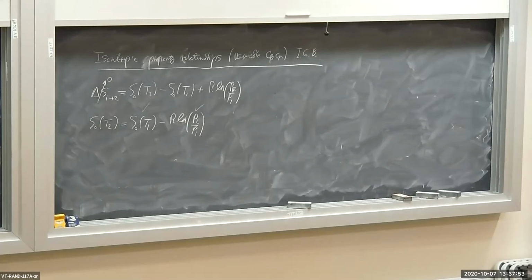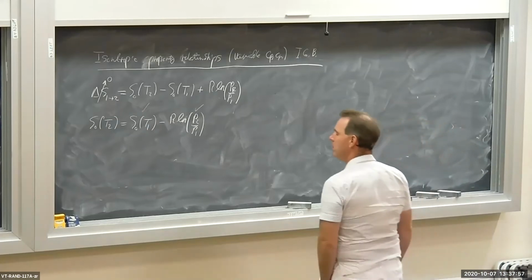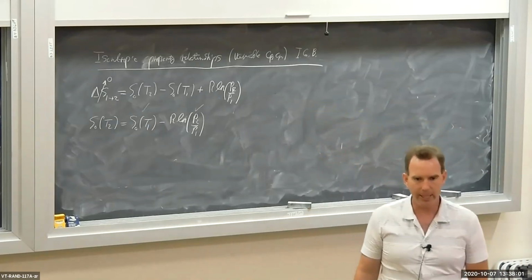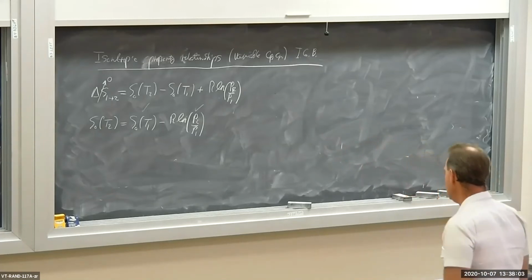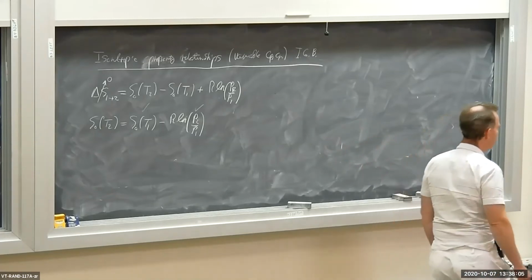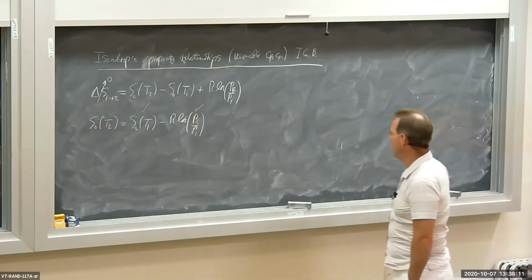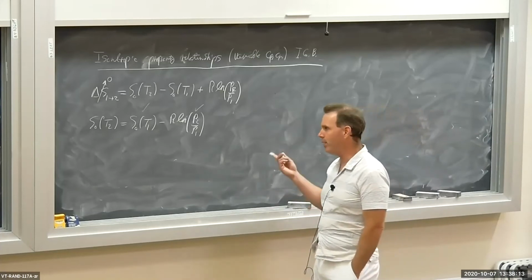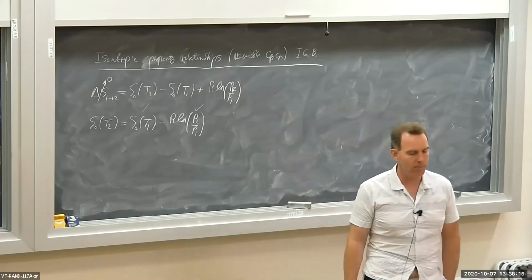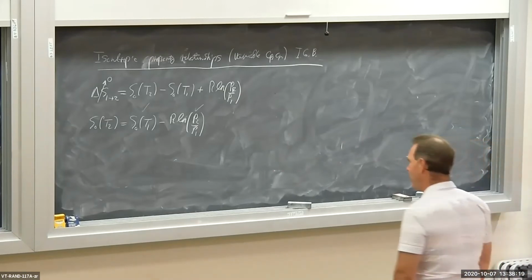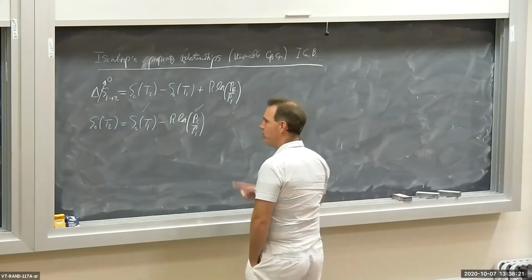Now, there's an easier way to do this, a much easier way. And it utilizes reduced pressure. Remember reduced pressure? We were talking about the ideal gas law about a month ago. We introduced reduced pressures and reduced volumes and reduced temperatures. Well, there's a quick and easy way that these properties, pressures and temperatures, can be related for an isentropic process using reduced pressure.